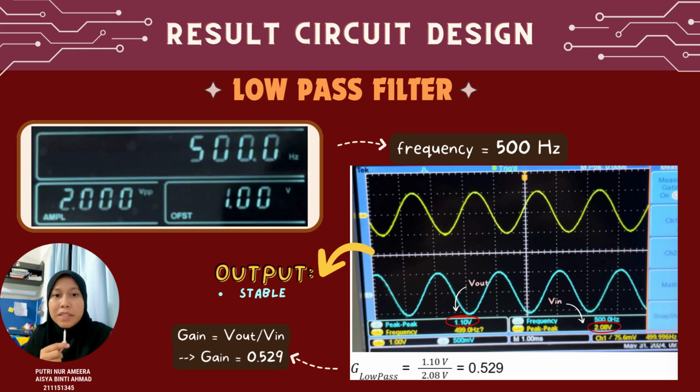So, our low-pass filter behaves as we predicted, keeping the high frequency out and letting the lower one pass through. This shows that the practical low-pass filter rejects frequencies higher than 100 Hz by reducing its gain and output voltage, which obeys the theoretical requirement.